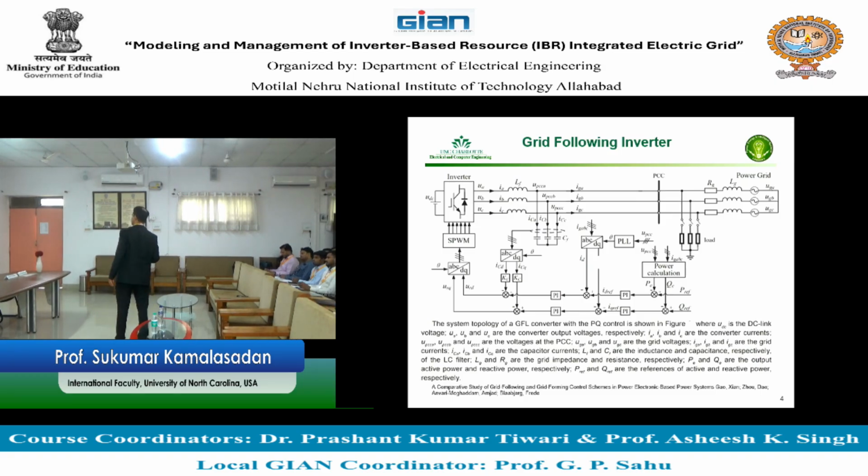So good so far. That filter output goes out of the inverter to the electric grid, and the bus that is connected to the electric grid from the inverter is known as PCC, or point of common coupling, or point of common connection. There are 2 different ways that are used. This is not an interconnection point. It is a point of common connection. Point of interconnection is something else, not this. So you may also see some people saying POI, point of interconnection. That's not this. That's a collection of the inverters that are connected.